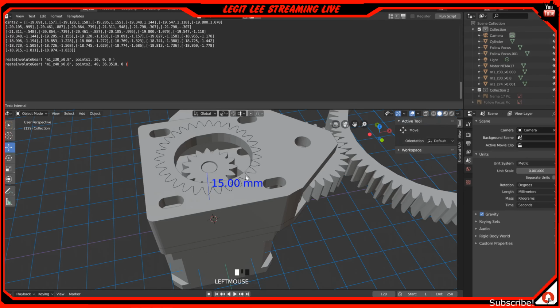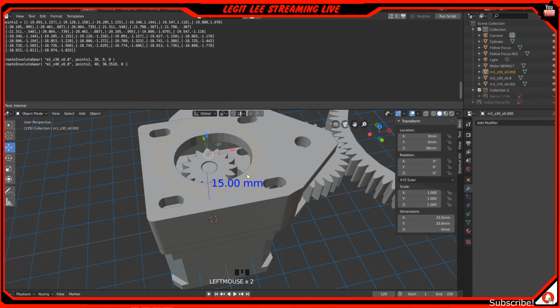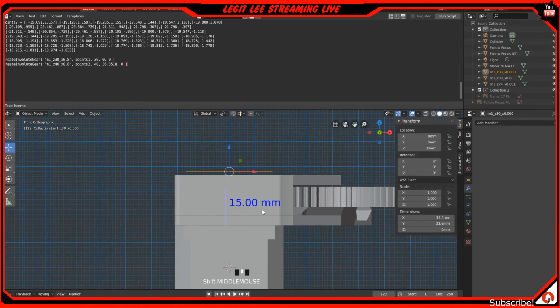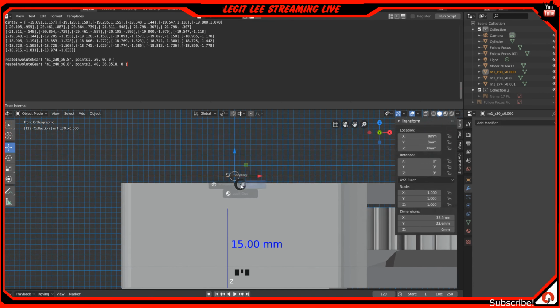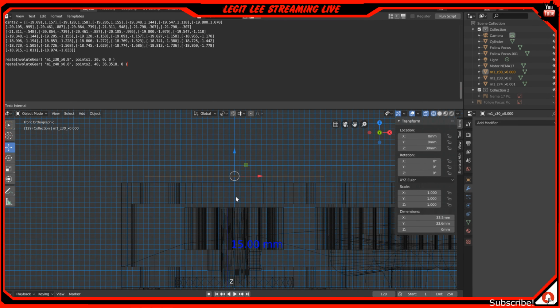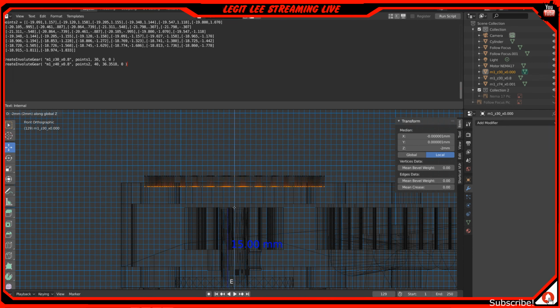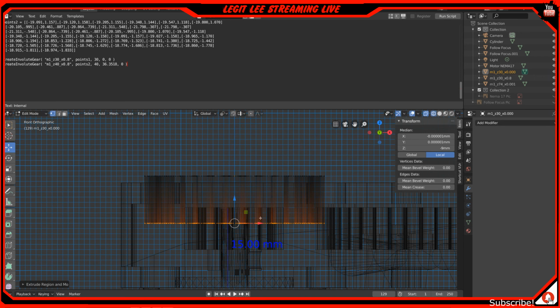And then we'll grab this one. Nope, this one. We need to extrude this. We'll go down since it's fine if we go down. Z, wireframe, edit mode. Hit E to extrude on the Z axis. 1, 2, 3, 4, 5, 6, 7, 8. And that is holding down control and just dragging down.